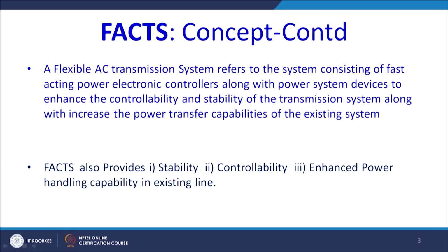Now, FACTS devices refers to the system which consists of fast acting power electronics controllers along with the power system devices to enhance the controllability and the stability of the transmission system, and it increases the power transfer capability of the existing system. And what is the advantage of FACTS? FACTS provides stability, controllability and enhanced power handling capability of the existing system. In subsequent discussions, we will elaborate on these topics.